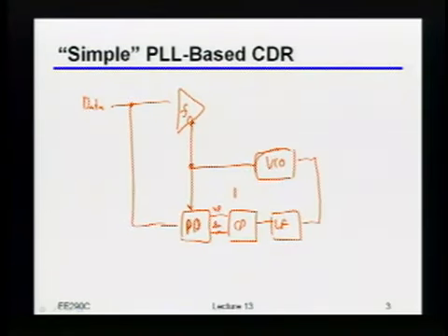Now, by the way, when I use a VCO like this, I'm actually doing two things. I'm not just adjusting the phase, I'm also adjusting the frequency, right? So that is actually kind of a good thing, because it means that even if I have, let's say, a slightly different reference, if I have one crystal on the transmitter, then by doing this CDR, I'll automatically figure out what the new frequency should be, right? As long as, of course, I've done a good job with building the phase detector and making sure I don't have harmonic locking and all the other nasty stuff we talked about, okay?